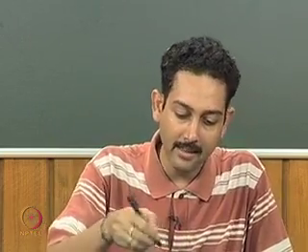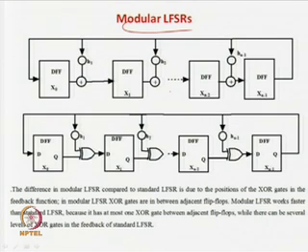Its job is almost the same. It will also have a characteristic polynomial, and it will also generate near exhaustive random patterns. The only advantage here is that the delay will be less, because in this case the architecture is a bit the other way around. There is no sequence of XOR gates. As long chains of XOR gates are not there, the delay will be minimized.